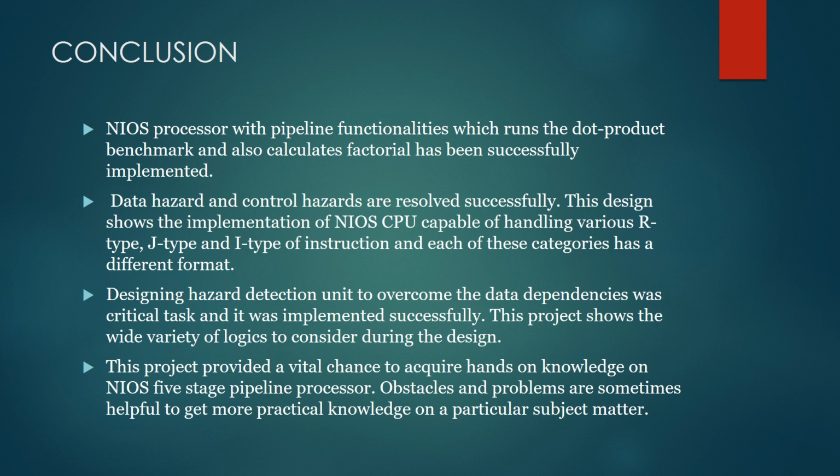In this project, I have implemented the Nios II instruction set architecture in Verilog, simulated the waveforms and got my results perfectly. The design was implemented in 5 main modules: fetch, decode, execute, data memory, and write back stages. The whole design is pipelined into 5 stages so that each instruction is executed in each cycle. In the design stage, hazards like structural hazards and control hazards were taken care of, and due to data dependencies in the future instructions, stalling is introduced in the design.